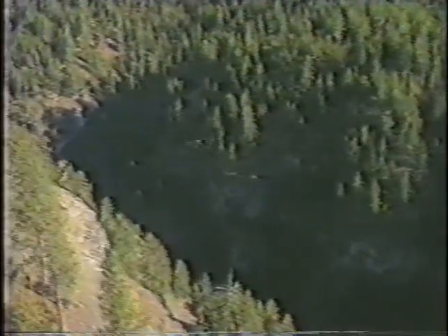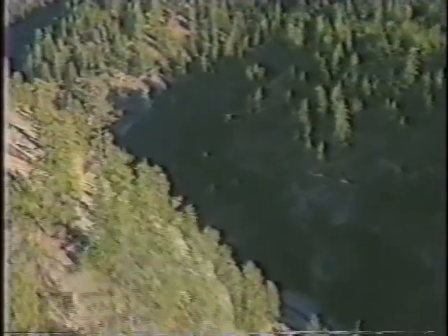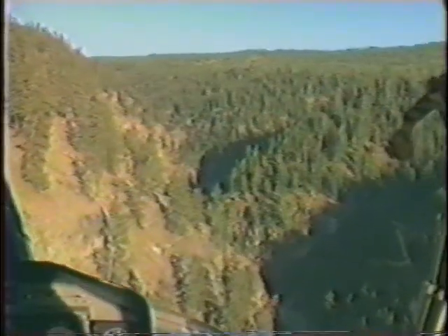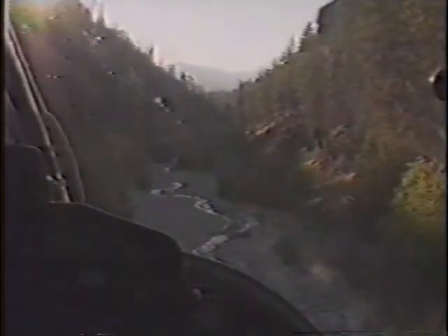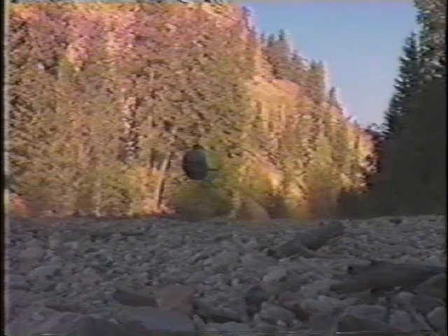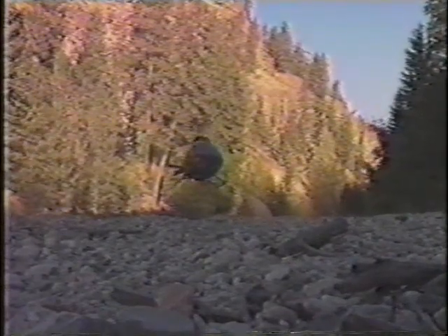Canyons can be very treacherous. There's often a lot of turbulence if you have any kind of strong winds at all. Do 50-knot recces up the hill, looking for landing sites and a place to enter the canyon. Then, work downhill once you're inside. Landing or takeoff need to be downhill, so you maintain your escape route drop-off.